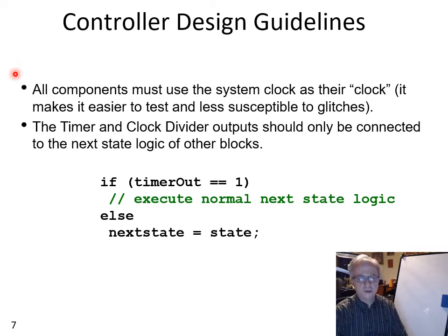But what the rules are: 1, all components in your module or your system must use the system clock as their clock. And when I say all components, really that's referring to the edge-triggered flip-flops. Those would be the only components in your circuit that should be using the clock. But all of them should run from the same clock. Violating that rule leads to enormous headaches.